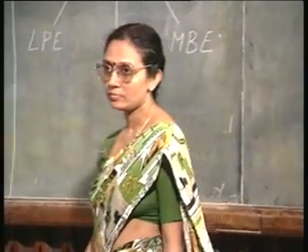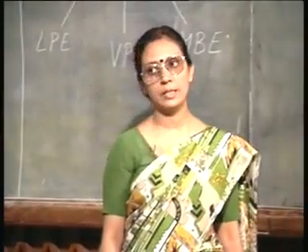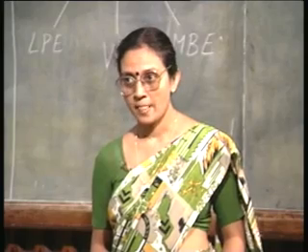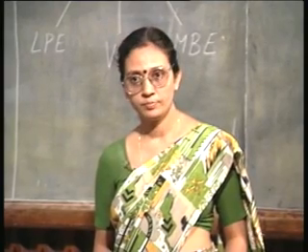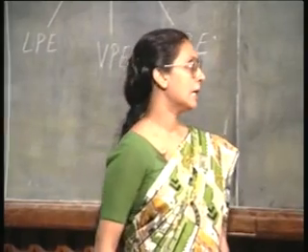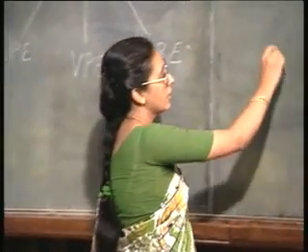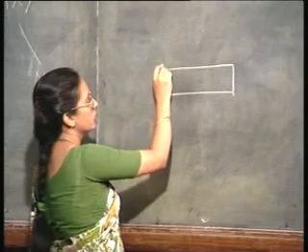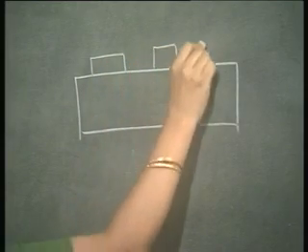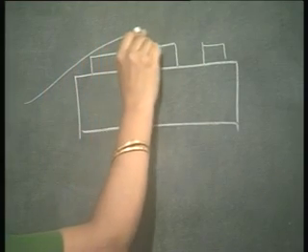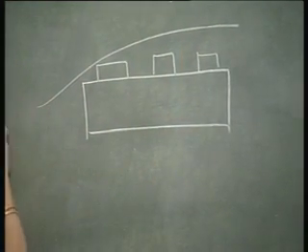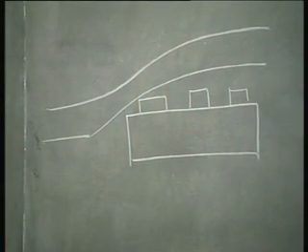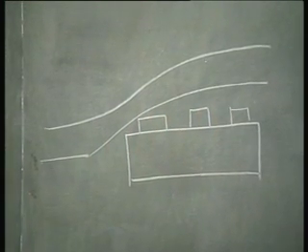And finally, how do we sort out the boundary layer problem? As I said, you can of course increase the velocity of the gas, but then your gas consumption will be more. So, the other possibility is of course, see in the figure we showed it like this. This is my sample holder, on top of that this is how the samples are provided, and this is how the stagnant layer is. Right? So, as I go down the chamber, the width of the stagnant layer is increasing.